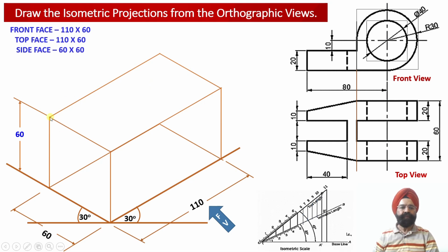So this way the top view face of the solid has been appropriately obtained over here. Next, once we draw another vertical isometric projector line measuring 60 millimeter joining these two endpoints, we can say that we have obtained the cubical construction corresponding to this solid, which is going to depict the front view face, the left hand side view face and the top view face of the solid in the isometric projections.